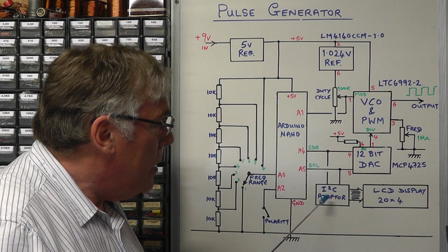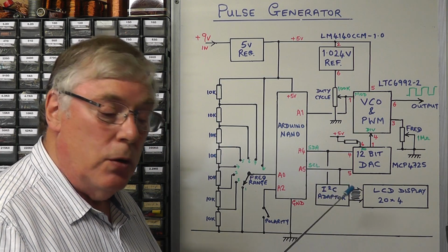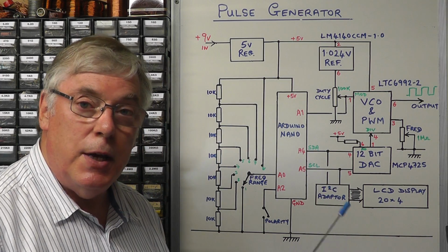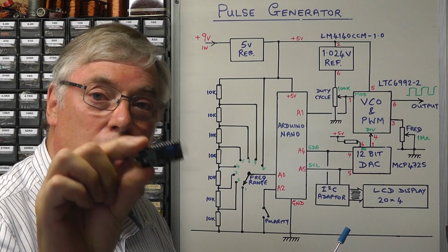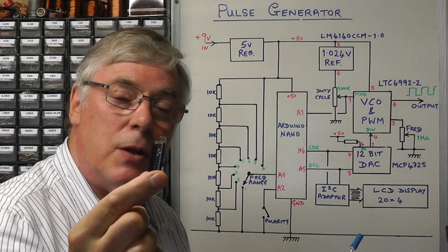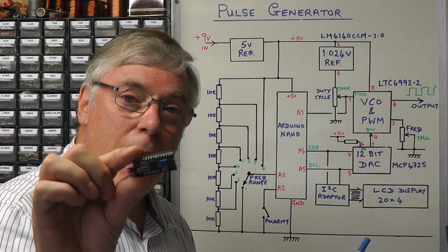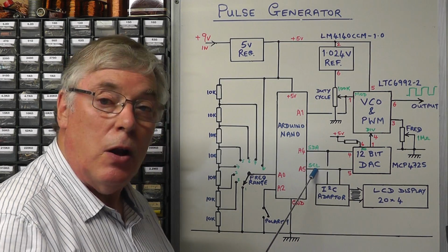And in order to do that, we need to use a little I2C bus adapter module, and again, you can purchase these quite cheaply on eBay these days. It's a little tiny module that solders onto the display and then gives you 4 wires coming out: a plus 5 volts, a ground, and then the 2 signal wires for data and for clock.